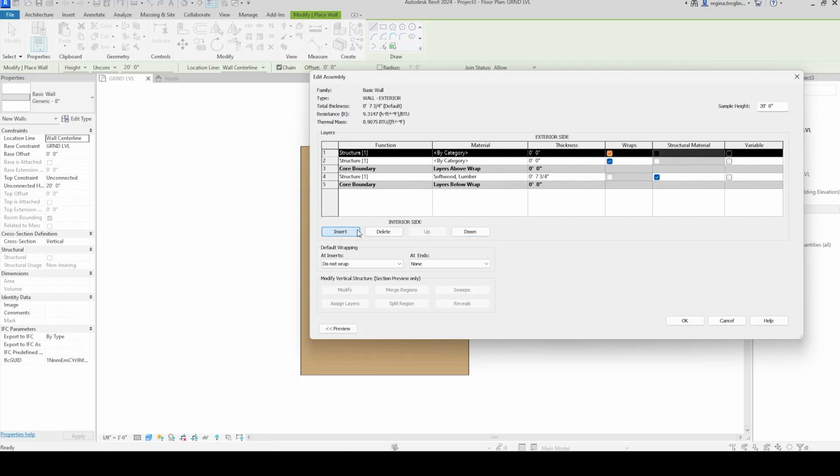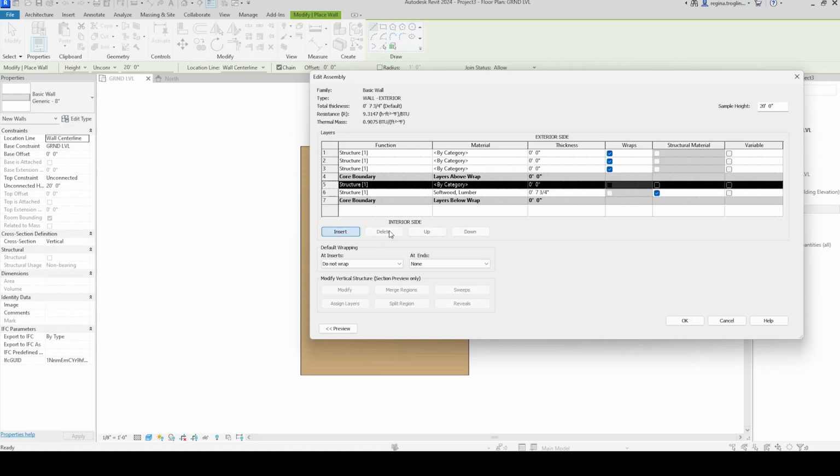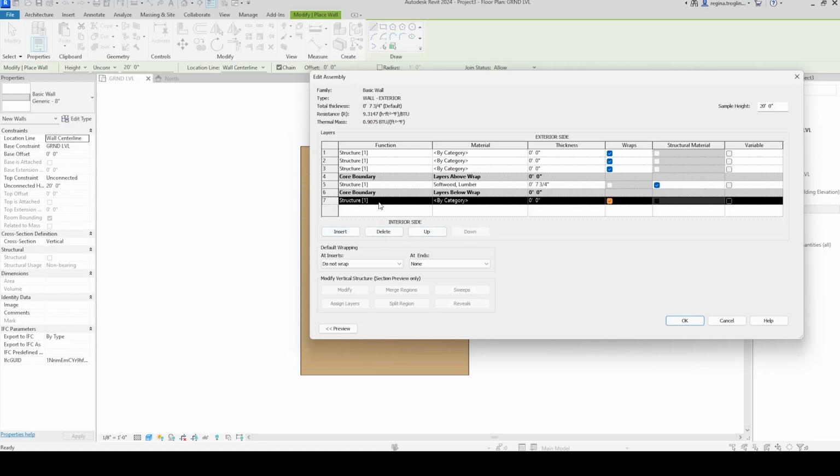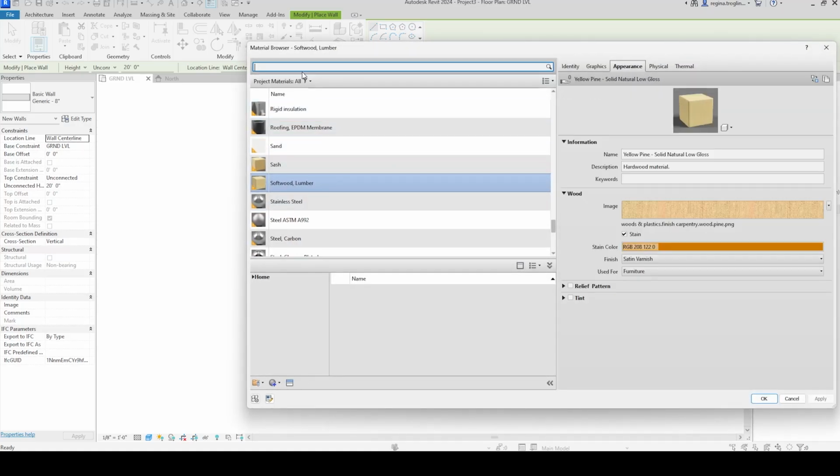The other thing we're going to do is we're going to go up and up. We're going to add 3 pieces here. We're going to add another one coming down as the drywall. So let's do the interior piece first. We're going to use finish 2. This is going to be gypsum. So GYP.